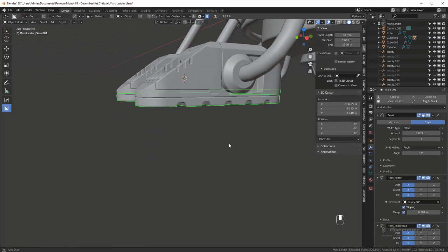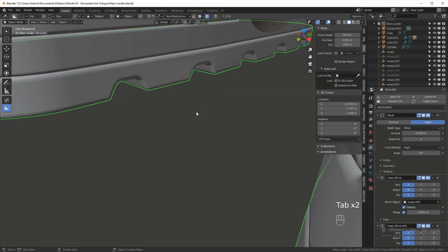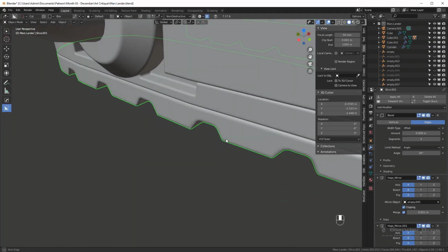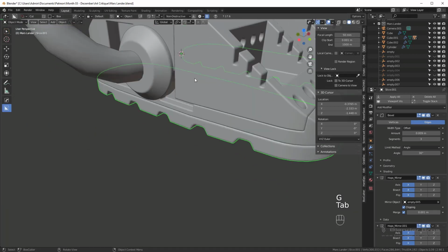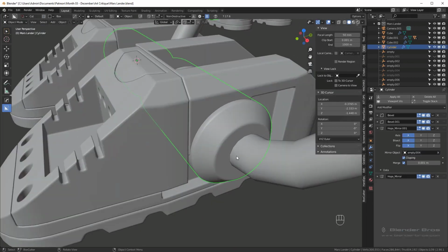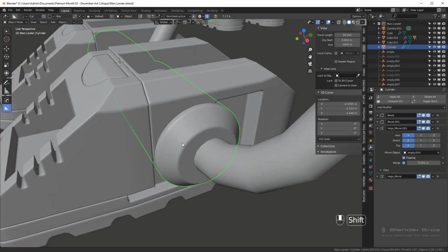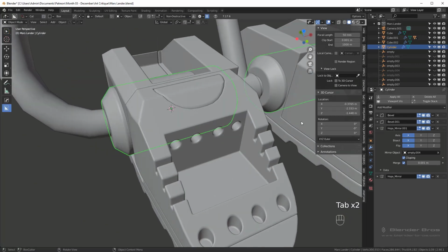And just a few other nitpicky things, like these artifacts right here, you need to make sure you get in and fix those up. Merge these areas together or slide them out. Make sure there's no artifacts anywhere unless they're very tiny and unnoticeable. Same for this piece, make sure you have an actual connection point, like something like this. It's super easy to hop in, take your, let's apply, which bevel is this? Let's apply the chamfer bevel.